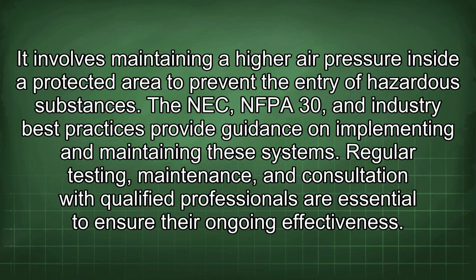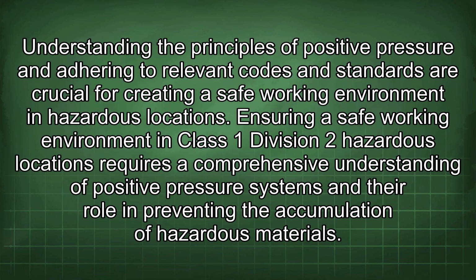It involves maintaining a higher air pressure inside a protected area to prevent the entry of hazardous substances. The NEC, NFPA 30, and industry best practices provide guidance on implementing and maintaining these systems. Regular testing, maintenance, and consultation with qualified professionals are essential to ensure their ongoing effectiveness. Understanding the principles of positive pressure and adhering to relevant codes and standards are crucial for creating a safe working